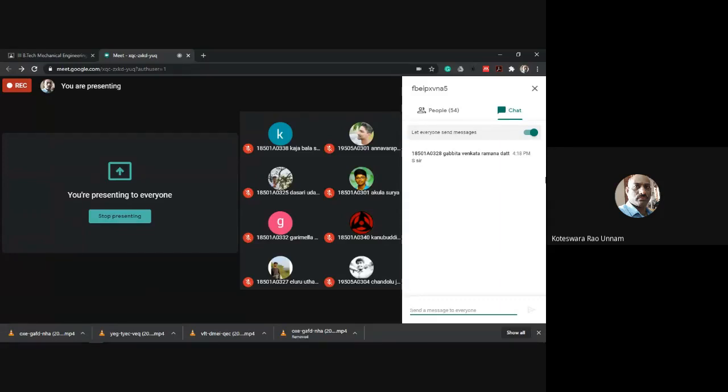Then capital F is strength of the solid plate. Like that, Ft is tensile strength of the perforated plate. Perforated means the plate which is having some sort of hole or notch, whatever may be, some sort of material discontinuity. We call it a perforated plate. Then Fs is shear strength of rivet expressed in newtons. Fc is crushing strength of the rivets.